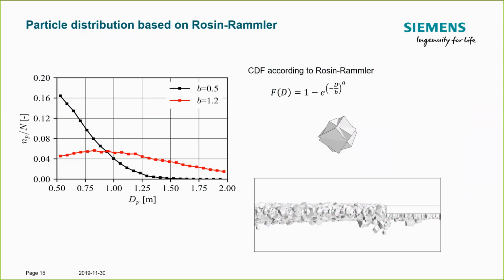You can see on the right-hand side also what the general baseline shape is that we are using to constitute this brash ice field. So it's basically two cubes, one of them being duplicated and rotated at 45 degrees in two directions, and then you'll get a shape that looks like this. So this can be an arbitrary shape, so you could come up with more disc-like shapes, triangular or polyhedral shapes, whatever suits the needs.